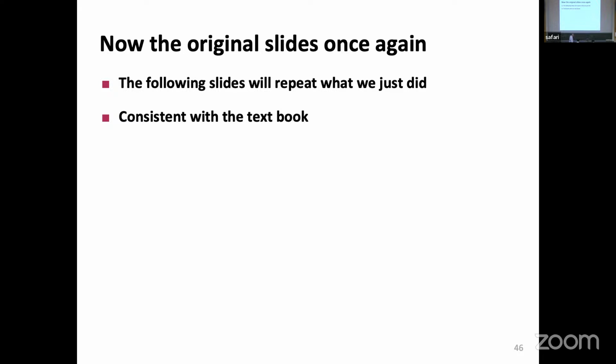You can control this one because you can build it internally, whereas external memory transfers always have a handshake. You say, I want to write to here, and then you hear back from it, saying, I did this. Or you want to read something, you say, this is the address, and it says, I have your data, with something like a data ready signal. There's always some handshaking going on.